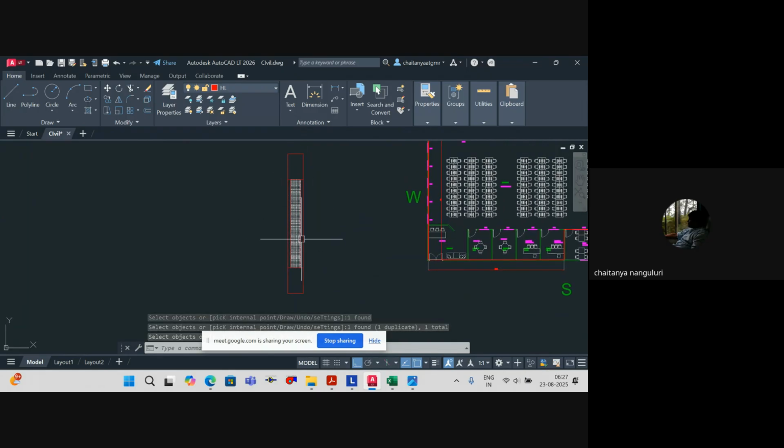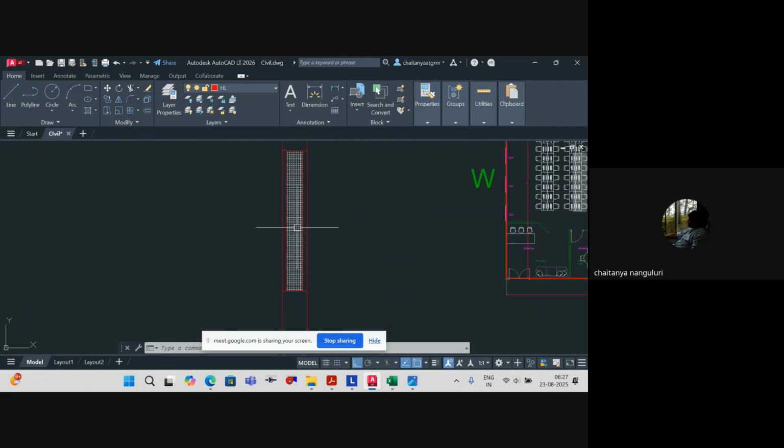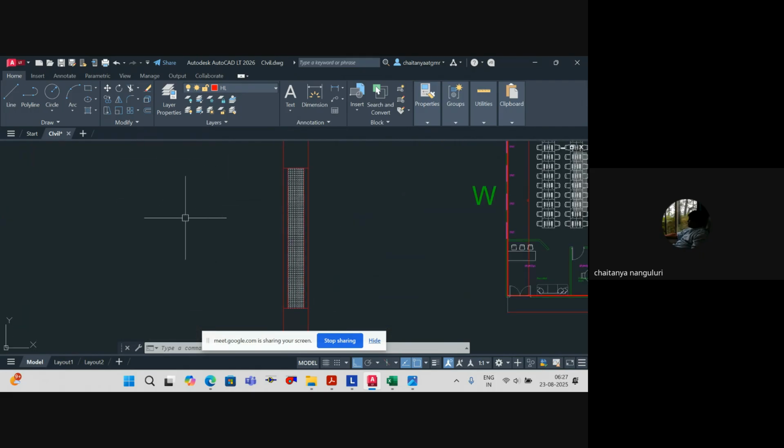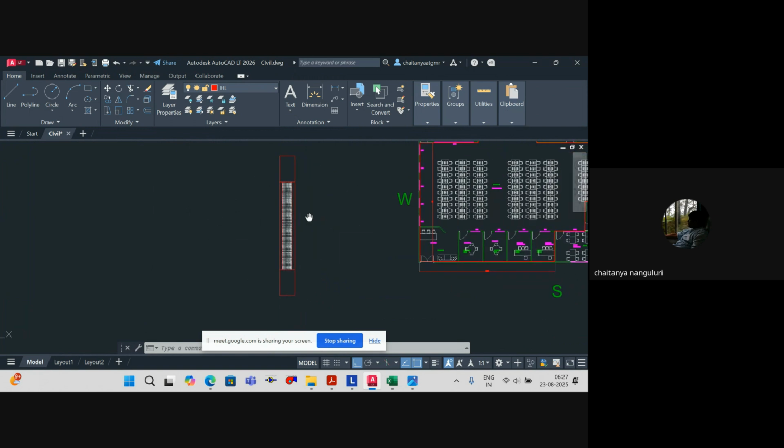So you have two layers of glass, and inside this you have vacuum. Because of this, even though you have high temperature here and lower temperature on the other side, you will not have any heat transfer due to conduction or convection. It's only the radiation that will come into picture. Understood or not?